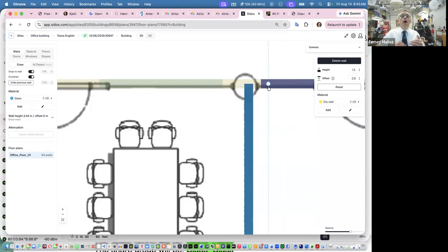That's why it asks you how high the floor is. Not the floor as in the ground level, but the whole floor to the ceiling. Because that's as high as I can go. I cannot place APs higher than that height. So if I want to have an AP above the ceiling, I cannot just say that the AP is 3 meters high, because it's not going to let me.